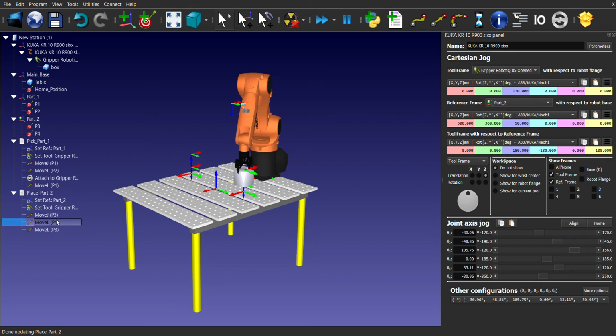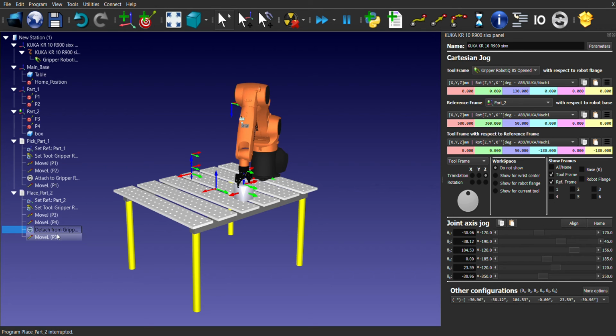So when doing part 4 here, we right click and add instruction, simulation event, we detach the object. For attach to parent, we choose part 2. So okay. So we do it again, up, down, detach, and move. As you can see, this is how the program works.